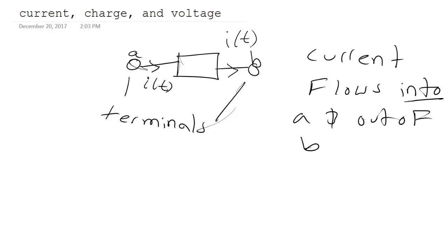must go out. However, you might have an issue saying, well, what happens if the electrons are actually flowing the other way? What if my current is in fact entering at B and leaving at A? If that happens, all that it means is that I have essentially a negative current rather than a positive current. So what will happen there, as we're doing more examples, we'll see, is that our currents come out to be negative. And that's okay. What it means is we drew the arrow the wrong way, and all we need to do is draw the arrow the other way and flip the sign.